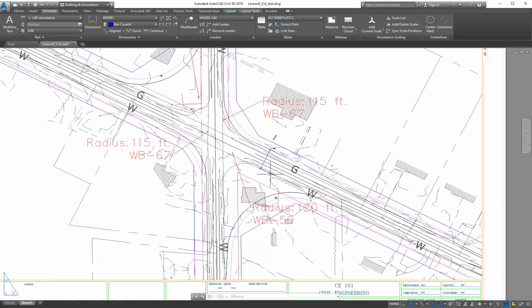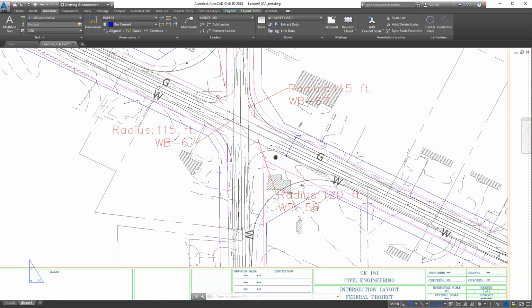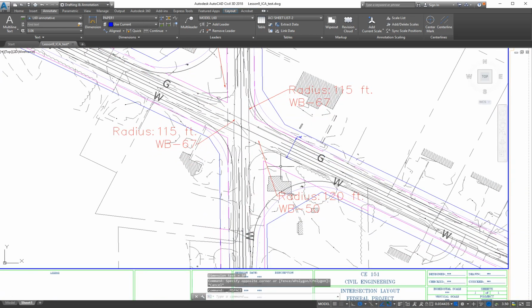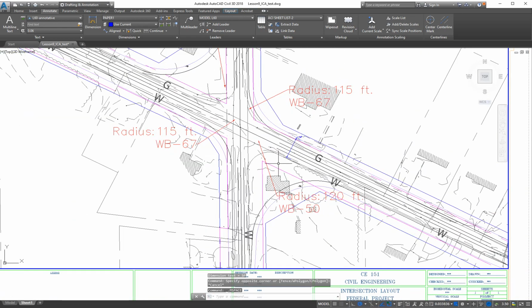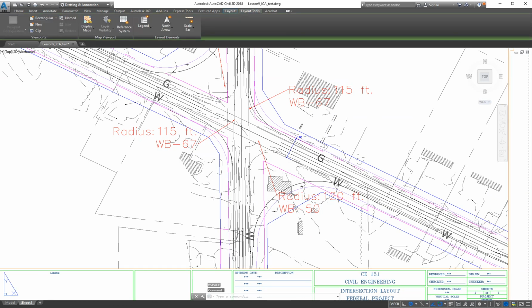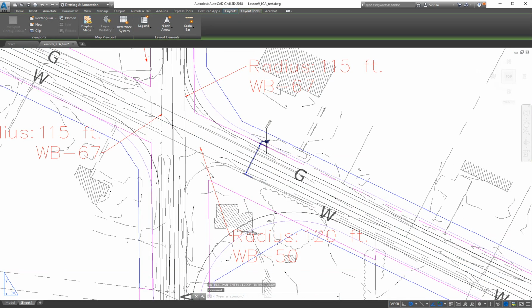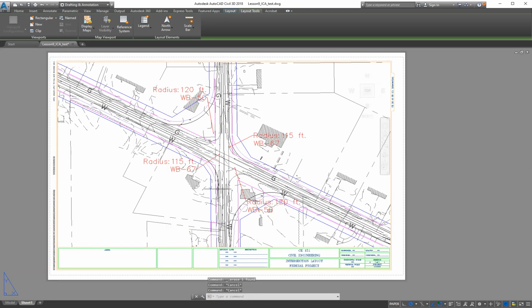It's relative and it moves around. It's in paper space. And if I jump back into model, it doesn't move because it's still stuck in paper space. So just to prove that, yes, dimensions and everything else will work just fine in paper space. And that's where we put almost all the dimensions. Rarely do we dimension anything in model space.